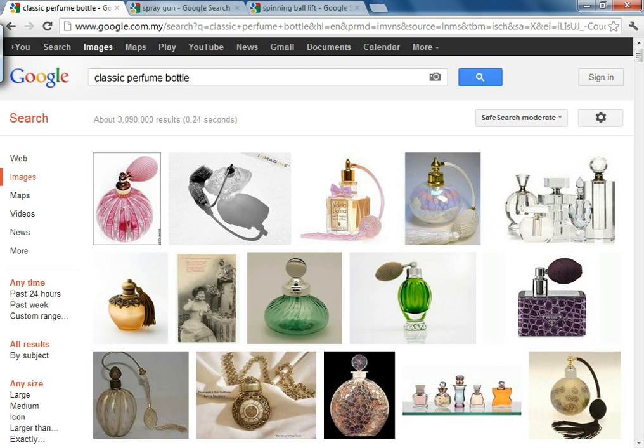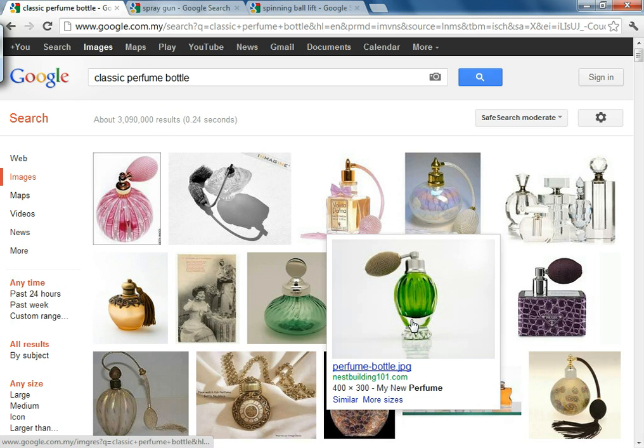So this is used in this type of perfume spray bottle. I think there's a straw going down here. So you hand pump this one, the air goes into a small chamber, so the speed goes up a lot, the pressure drops, and then sucks up the liquid, and that liquid and air mixture comes out in a spray. Is that all right?